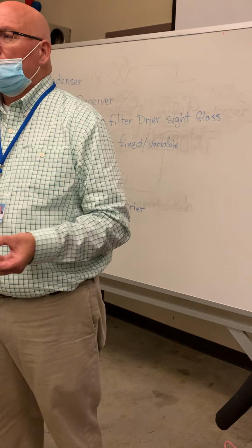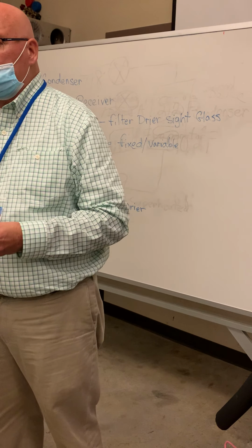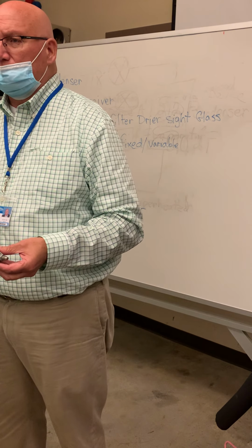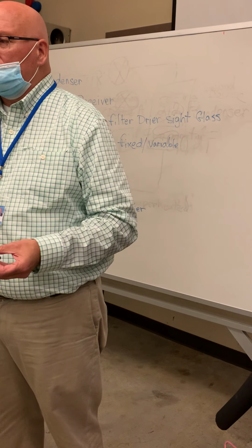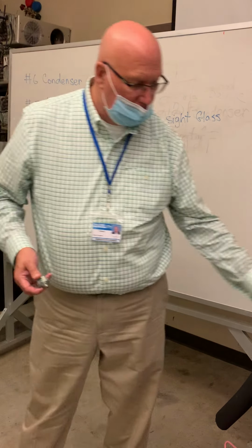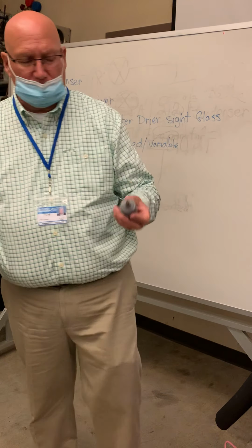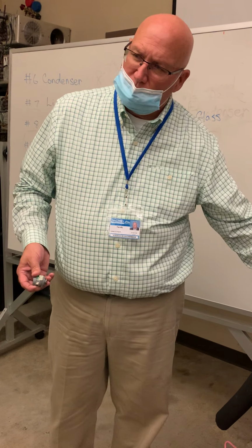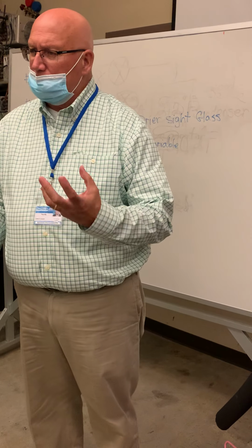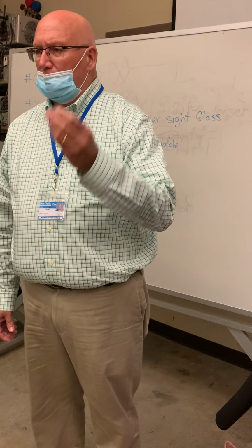Now, what do you do? Well, you can recover the refrigerant using a recovery machine. When you're recovering the refrigerant, you can pass it through a filter dryer once, twice, several times. You try to get rid of that moisture that's embedded in that refrigerant, and you can re-vacuum your system to get it to dry out.